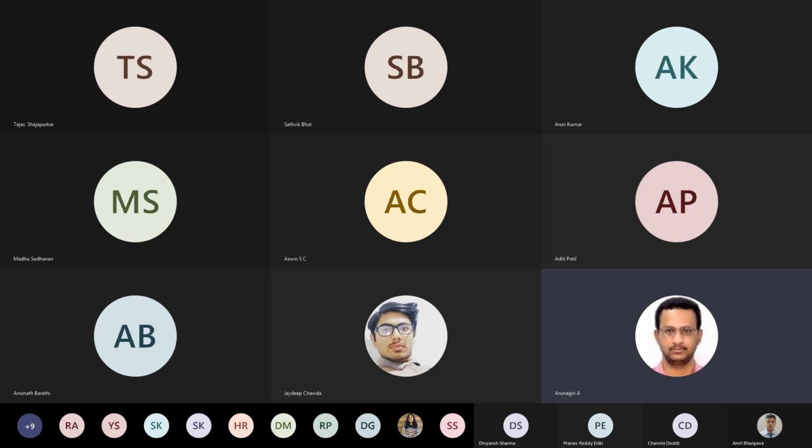Later, when the experimental values were compared with the values calculated by these methods, the deviations were more. So they did more research on these cases. They found that the shell side estimation of heat transfer coefficient and pressure drop deviates more from the experimental values as per the Kern method.